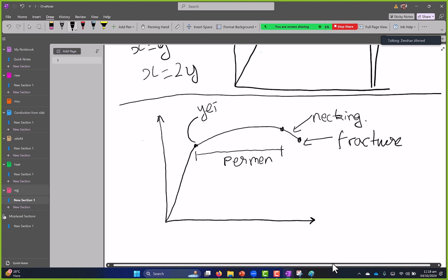For example, if you take a small part of that elastic, the elastic used in clothes, and you pull it a little, it goes back, right? Every time you pull it, it will go back. But if you start pulling it very strongly, you'll see that it will deform permanently. Then there is no coming back from there. That elastic used in clothes is a very good analogy to steel.